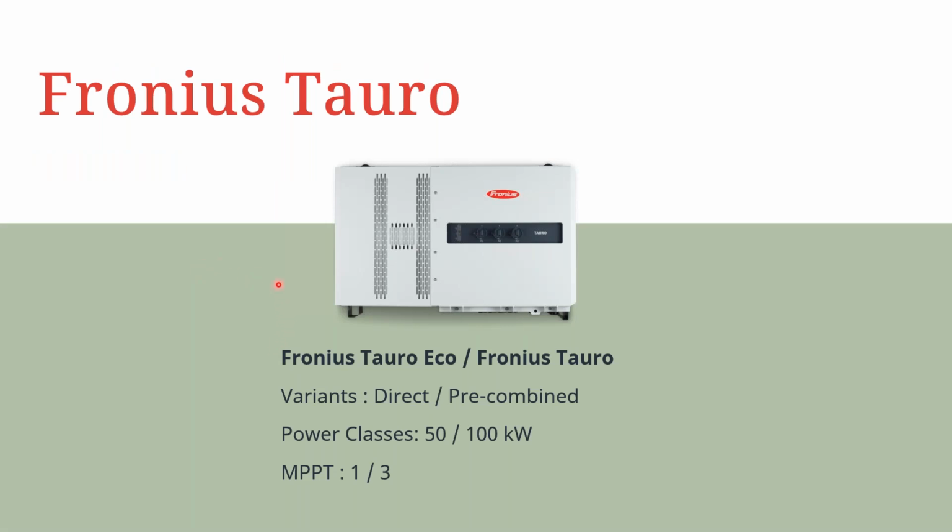Next is the Fronius Tauro. So this is Fronius's commercial-based inverter. We have 2 different variations: the Fronius Tauro Eco and the Fronius Tauro Standard. The variants are different between the Tauro and the Eco, but both are available as direct or pre-combined, allowing us to have MC4 connectors on the bottom of the units for string inputs, as well as a pre-combined string design coming into the unit entirely.